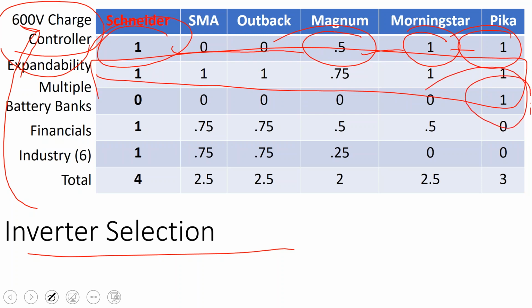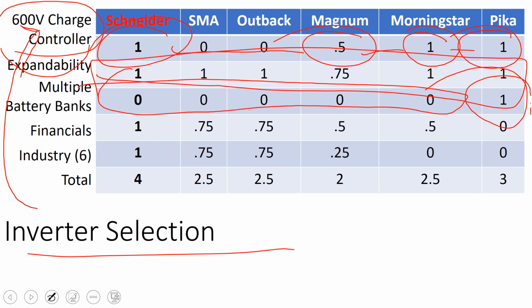Only Pika is supporting multiple battery bank chemistries. It's not that you can't do multiple battery bank chemistries. It's just you're on your own and you might void the warranty. So there's installers who will put, say, a grid with lead acid and a microgrid where on-site lithium ion complements the lead acid grid signal. But that's really the hackers who are on the cutting edge of design. It's not really a product you'd put forth to a client.